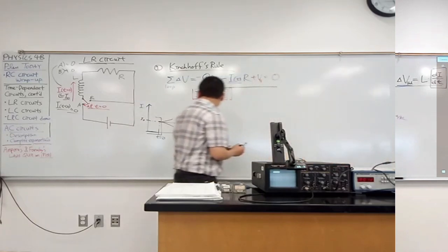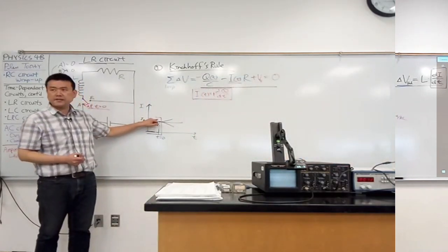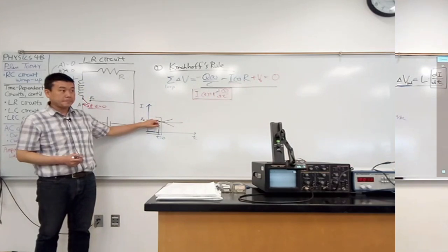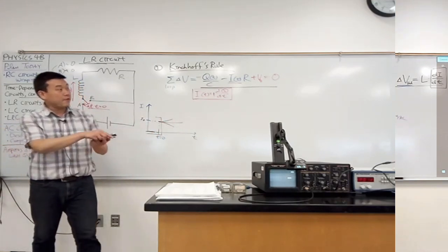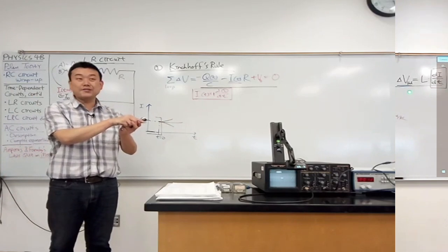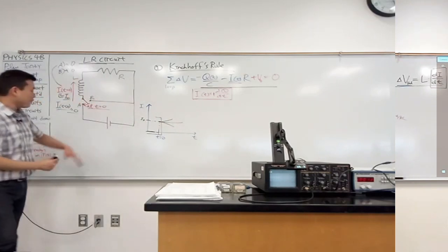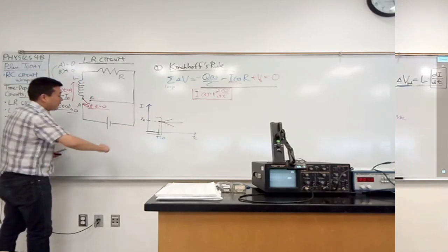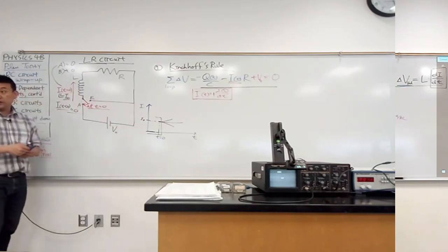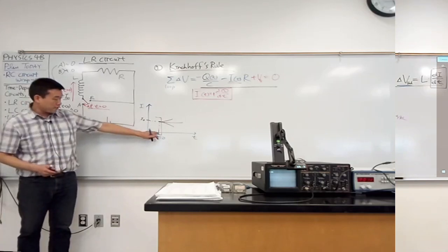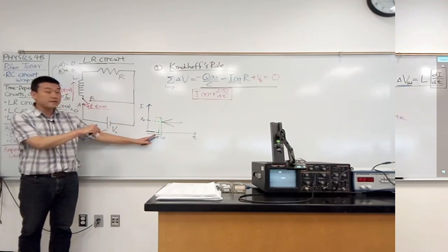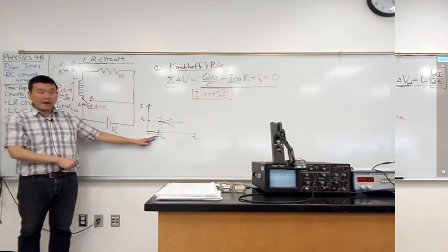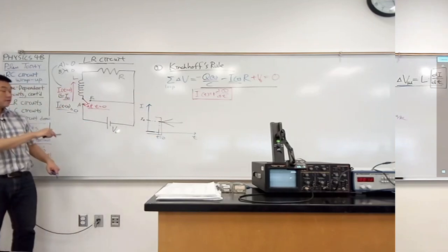Actually, when you see a change that looks like this, how large is your dI/dt? Very large, right? It's this slope. It can be infinite depending on how you idealize this. So that means if you have infinite dI/dt, you have infinite change in voltage. But in this circuit, I have only a finite amount of voltage here, V naught. So that's the contradiction I was looking for. If I want to say my current suddenly changes to a new value, this requires an infinite rate of change when it happens. So I cannot have an infinite rate of change without an infinite voltage.